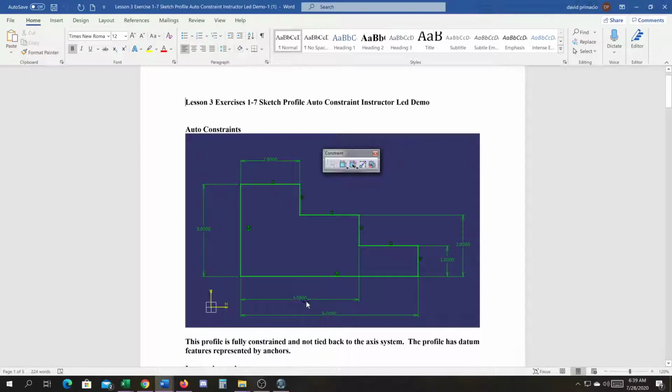If you want to do baseline dimensioning or chain dimensioning, it's really good for that. One of the problems it has is dimension to points, dimensioning to angles, dimensioning to elements that are not going to come off your datum. So if you manually stick those in, it will pretty much do the rest for you. So you got to give it a little guidance.